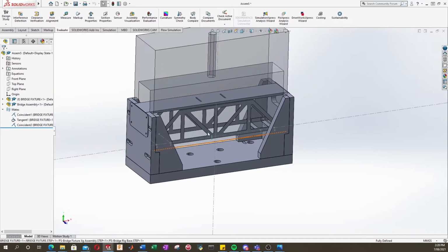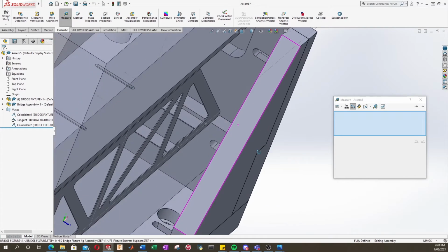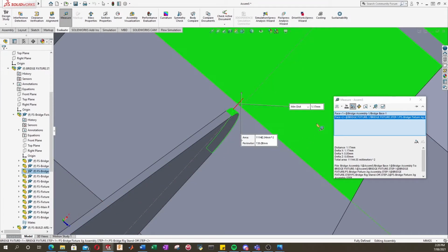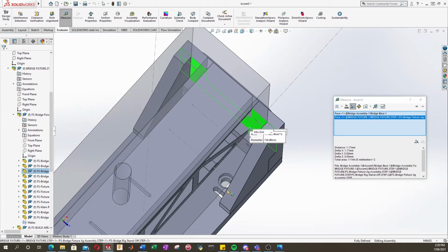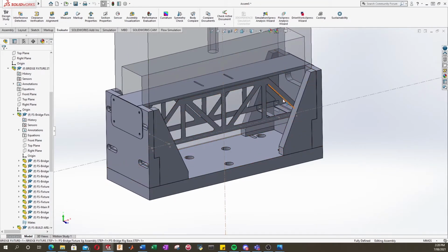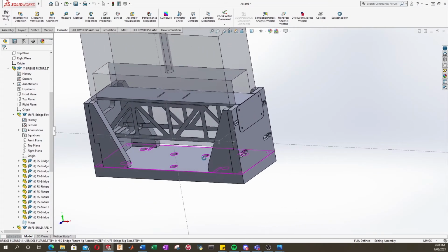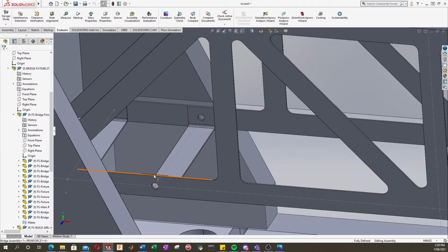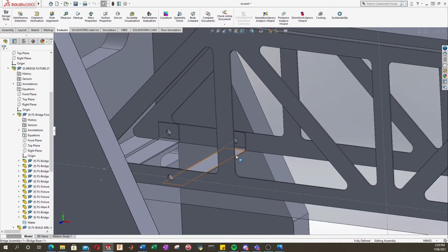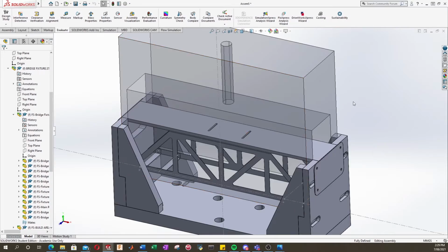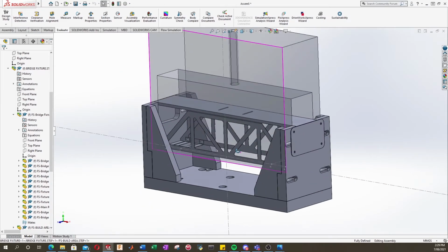So that's moved, and we can take our measurement again, but already we can see that's really close. So we're looking at 1.17 millimeters. So I'm happy with that. That'll give us a bit of room for tolerancing. And we can also see that our parts that we created updated. So those holes we did had moved position, and so our reinforcement beams have automatically updated and realigned to the holes, which is very, very convenient.